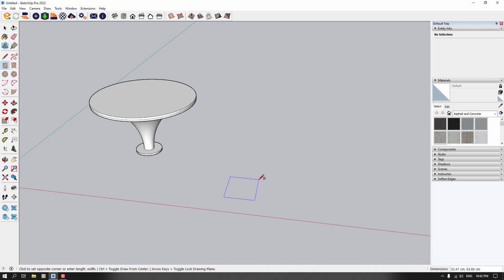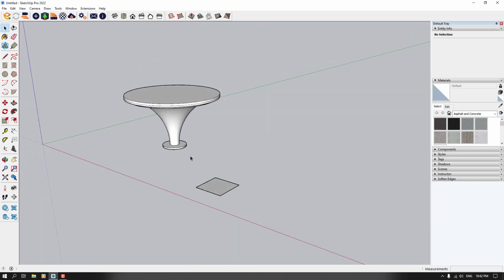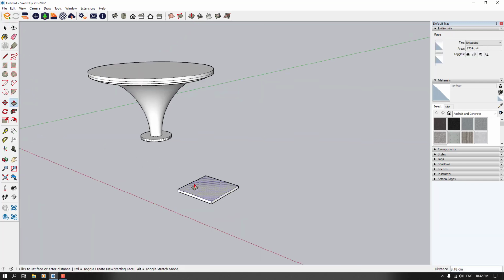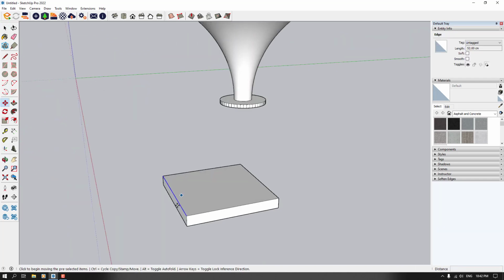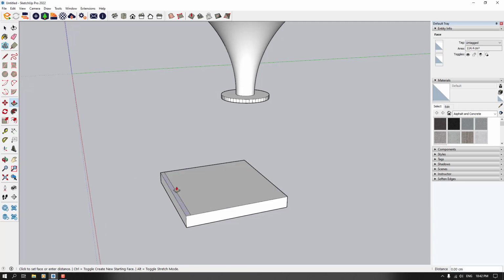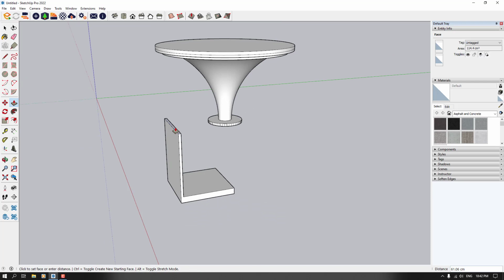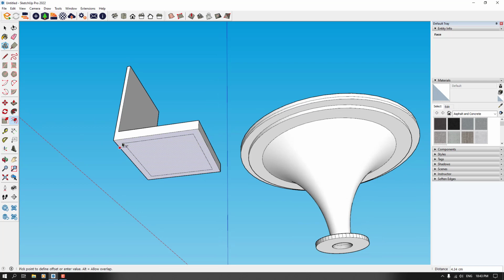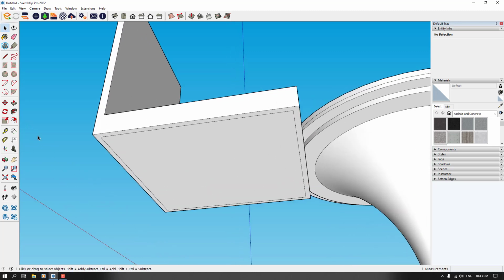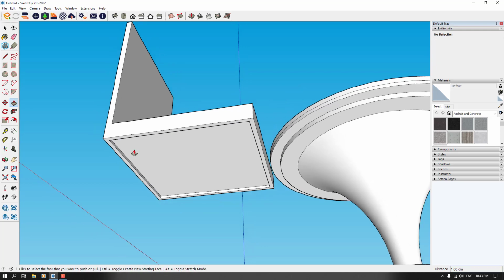We have some chairs with some dimensions about 52 by 52, and I'm gonna extrude this face about 4 or 6 centimeter. I'm gonna click on this line. I need some copy of it, about 1 or 2, maybe it's good. I'm gonna extrude it again about maybe 54 centimeter. Now I come to the downside, I use offset option. I want to draw the holders for the chair, so I'm gonna offset it like that. Now I'm gonna extrude it a little bit inside, about 1 centimeter.